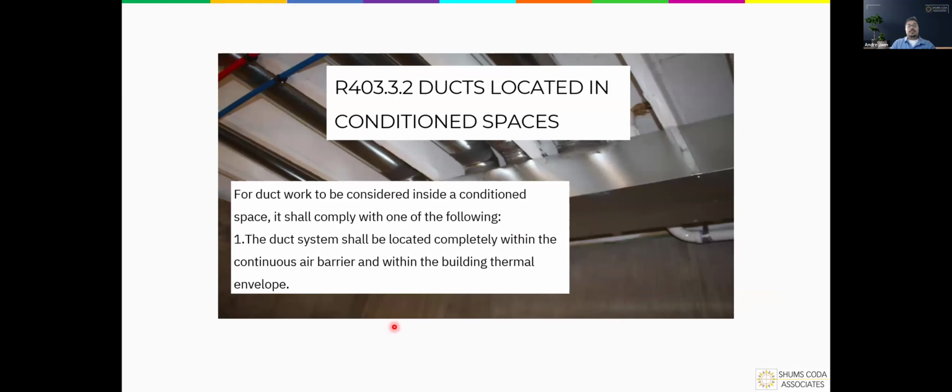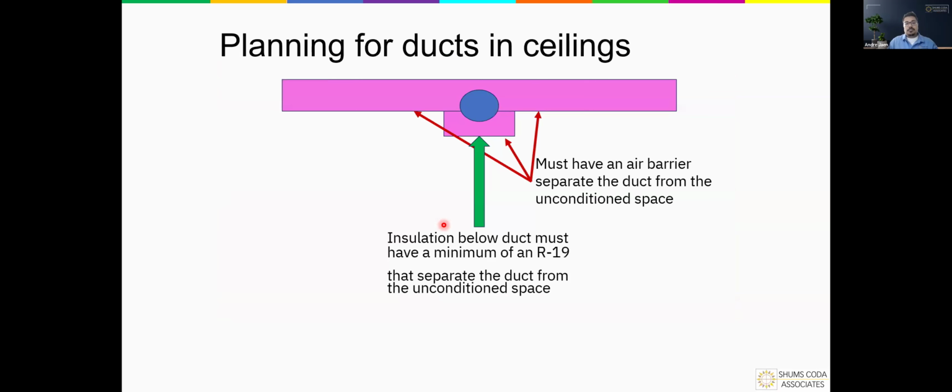And now we're going to jump over to ducts located in some of these conditioned spaces. Once again, we already talked about that line in the thermal envelope and the depiction of it. Obviously, to meet some of the criteria, if you're in the 21 and you're getting that additional efficiency package of keeping everything in, then that's an easy one to shoot for. If you can prove Manual D shows it's all inside, and your depiction of the thermal envelope shows it all inside, then you're in great shape. As you get into more complex ones, like in 24, where you might have multiple different credits that you're going for, trying to get credit for one of them might be something like this.